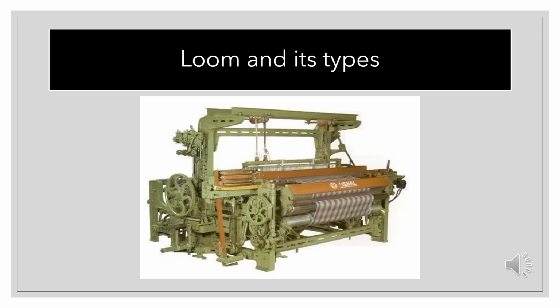Shuttle loom. The shuttle loom is the oldest type of weaving loom, which uses a shuttle that contains a bobbin of filling yarn that appears through a hole situated in the side. The shuttle is batted across the loom. Although very effective and versatile, shuttle looms are slow and noisy. Also, the shuttle sometimes leads to abrasion on the warp yarns and at other times causes thread breaks. Shuttle-less loom. Many kinds of shuttle-less looms are used for weaving, such as projectile looms, rapier looms, water jet looms, and air jet looms.